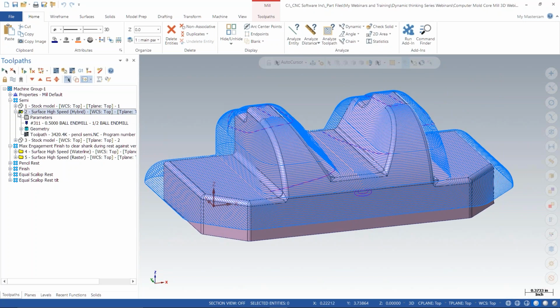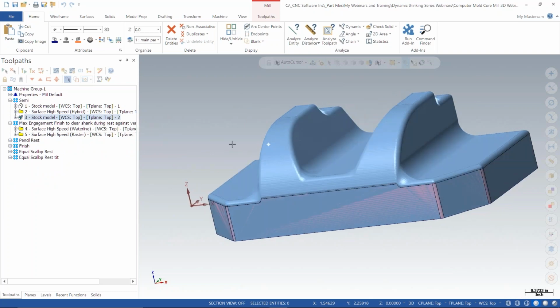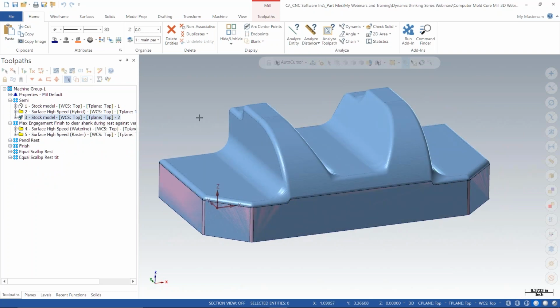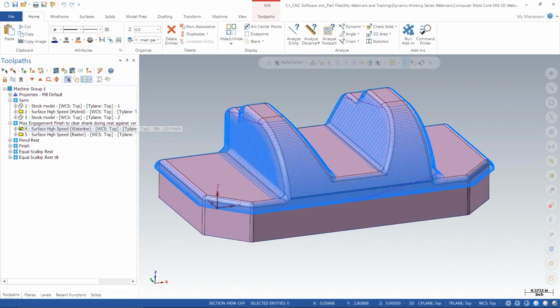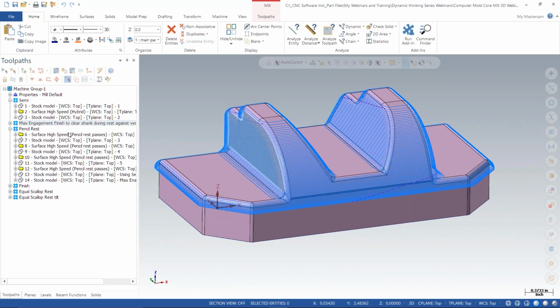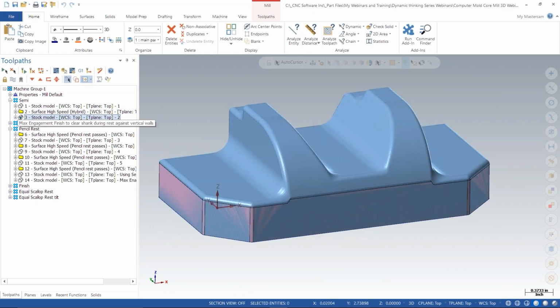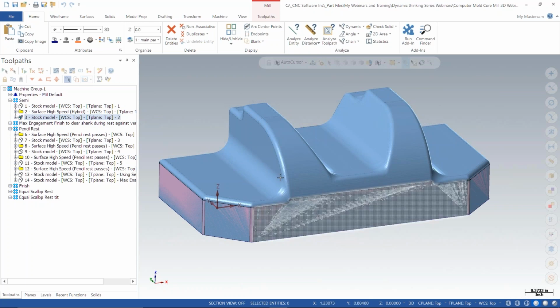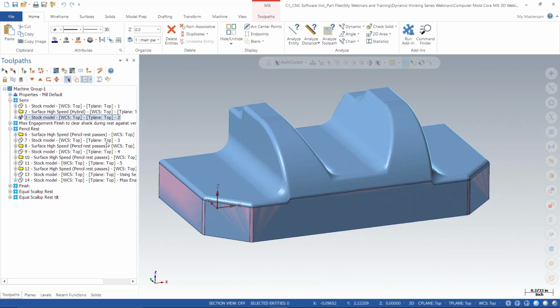So that's my scenario. I'm here right now on the CNC machine, and now I've got to decide, this is like a mold and die technique. If this floor wasn't flat and this wasn't vertical, it's some organic shape, it's hard to get all those free flowing corners cleaned out. So I'd like to rough that out a little bit before I get to my finishing. I know I've got this 1/2 inch, and the radius on the part is 1/8 inch. And I want to dig this out with a smaller tool in step-ins, kind of.